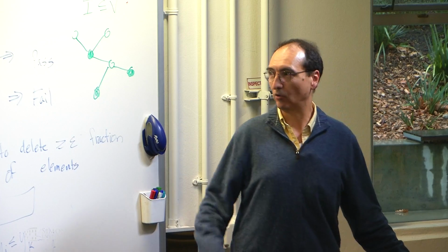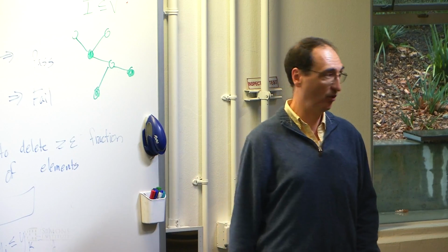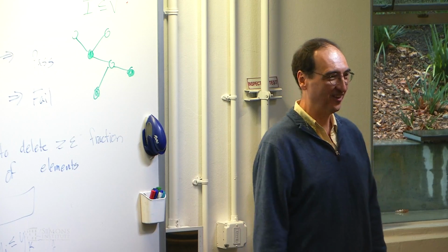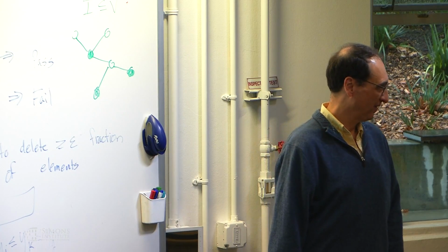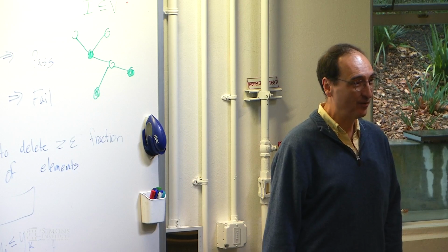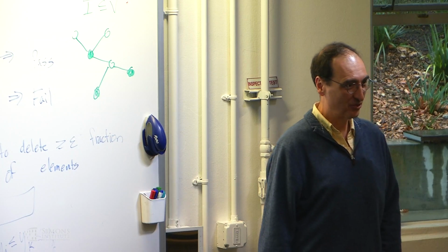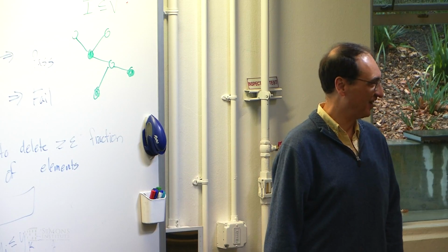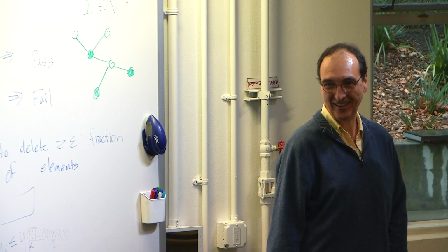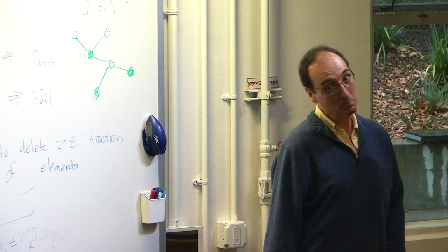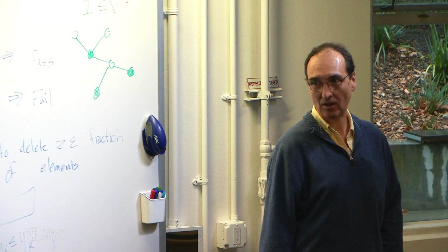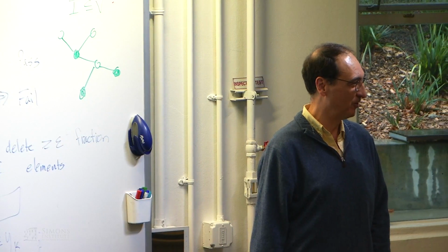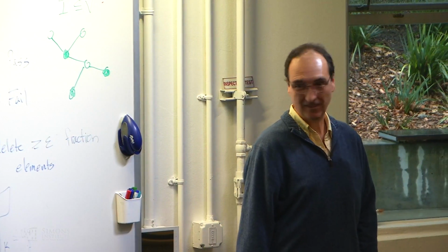We also, of course, have to remember to think about things like stability, robustness, and a big one for control systems that we typically have not done is security and privacy. Right? So Stuxnet was a SCADA loop, right? So SCADA, supervisory control and data acquisition, or whatever SCADA stands for, right? The C, I'm pretty sure, is control, right? And so guess what? I'm going to assume that any command that comes across my bus is valid. Right? Ooh, that's maybe not such a good assumption if somebody put a USB key into a computer someplace, right?